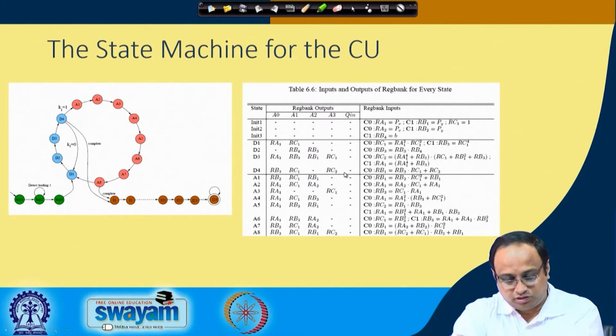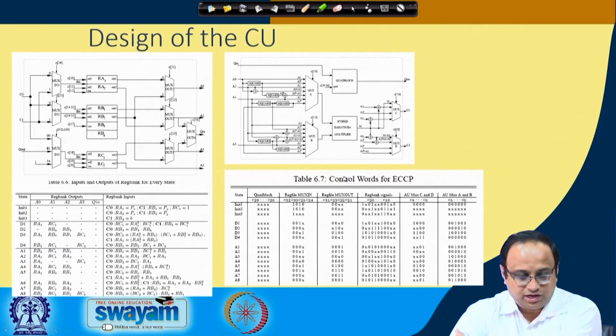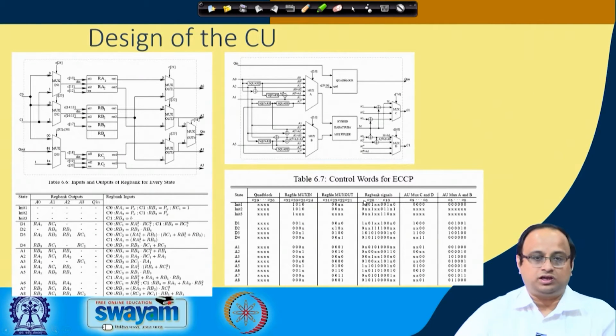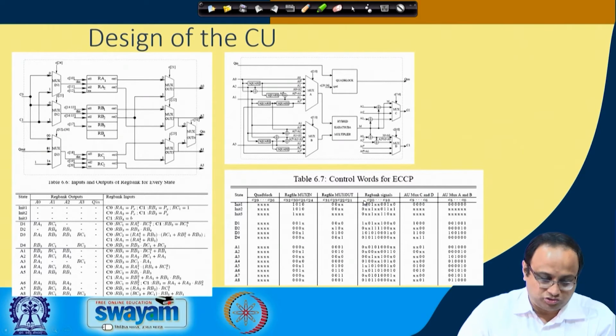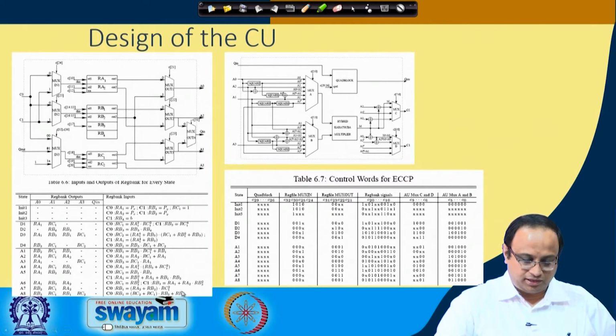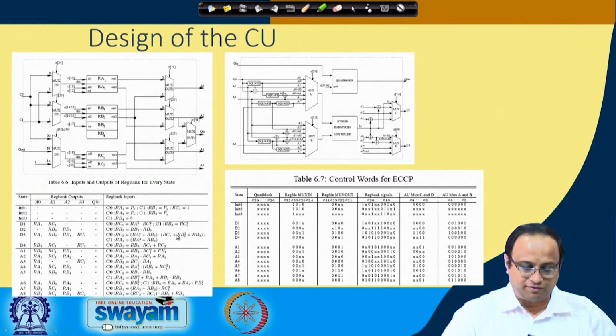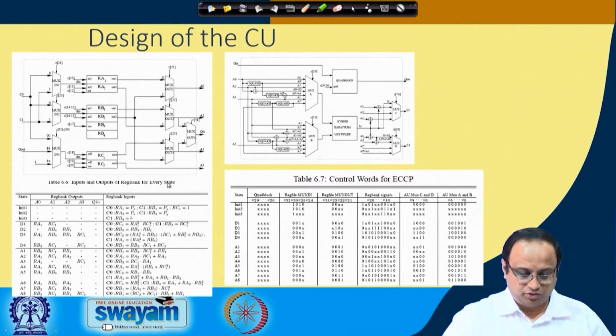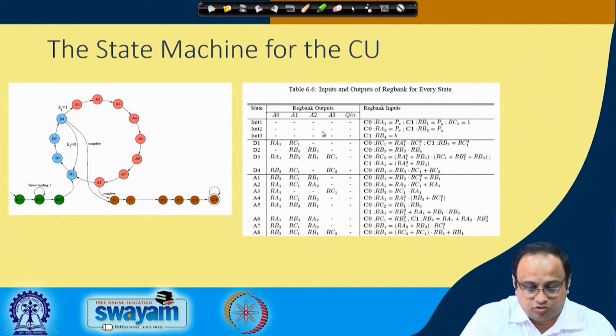So, you have various steps. Let us try to see at least how to read the control logic. I will not go into too much detail about that, but rather leave it to you as an exercise. But you can see that you have all the components which are required. So, let us explain the control unit, which is essentially the centerpiece of the architecture. The control unit has 4 distinct parts, shown by this FSM or finite state machine.